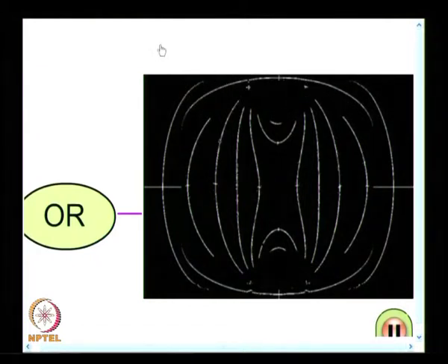So, what you find is you scan the image horizontally and vertically, each scan provides you some fringe points and some noise, and a logical operator helps you to connect all the fringe points. All the fringe points are now collected, but you also have noise. If you go to another set of orthogonal scans, you are able to get all the fringe points, but noise in a different direction. So, when I do the logical AND, the noise is eliminated, that is the principle behind it.